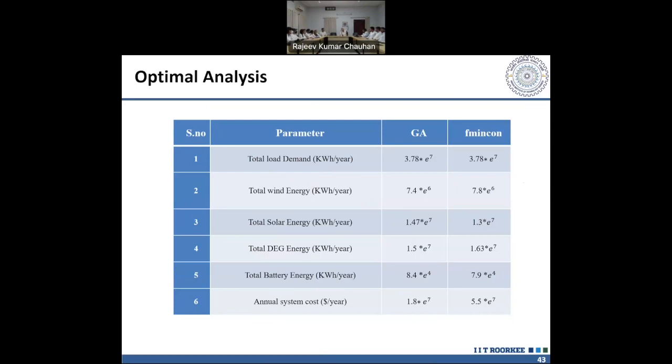In the next moment the cloud is gone again. So if you have a plant of about 500 kilowatt, suddenly it drops to 200 kilowatt, and in the next 5 minutes it is again coming to 400 kilowatt. This is called the volatile nature of the sources. Wind and solar are both very volatile in nature, so you also have to consider this in your planning.